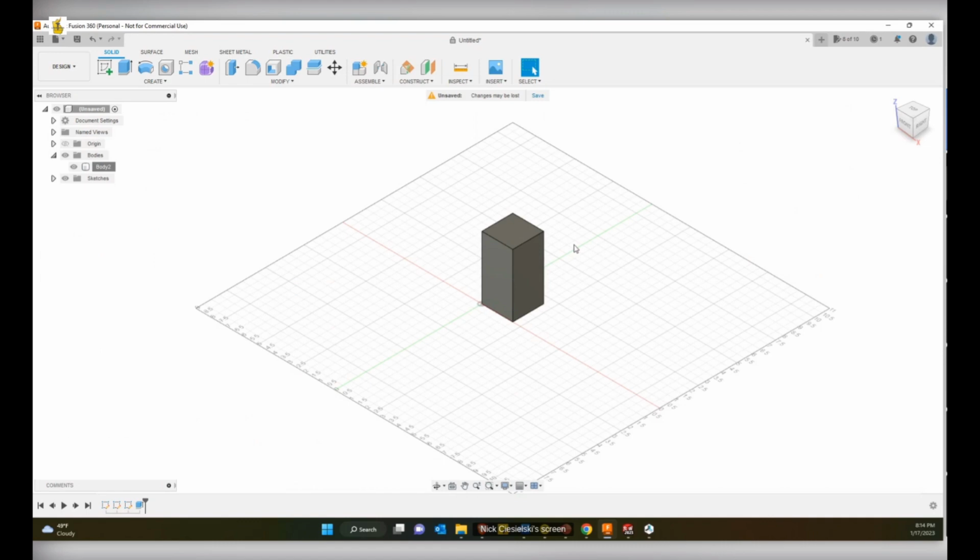I would first need to load my filament that I have here, coming off the top out of the dryer box into the extruder through the motor back here. And then, like I said, hit this with hairspray so that it adheres to the bed. But after that, everything should work fairly well as far as printing that part.